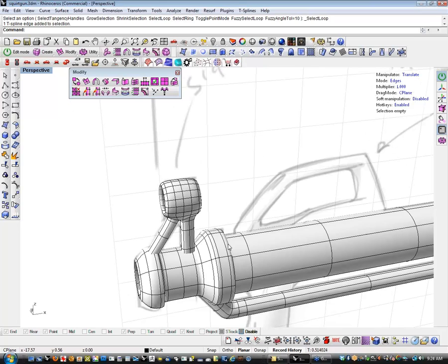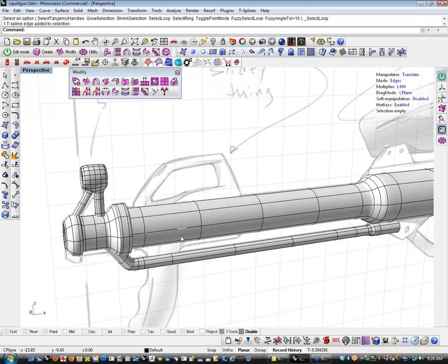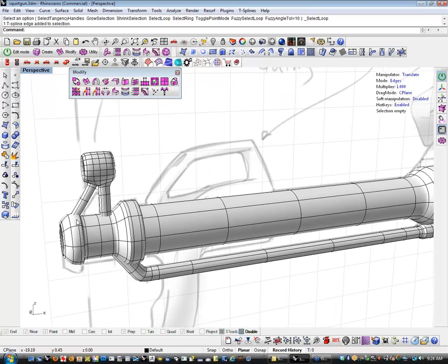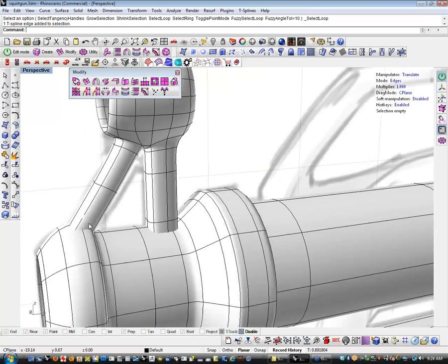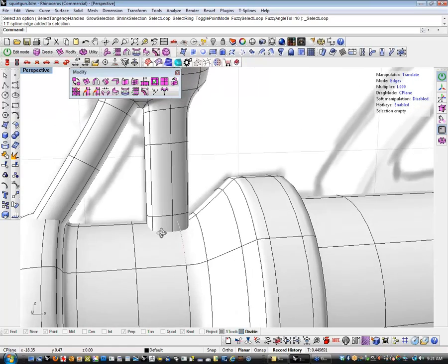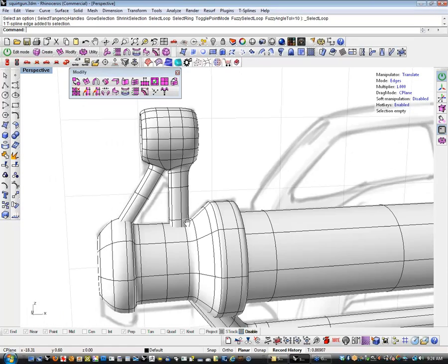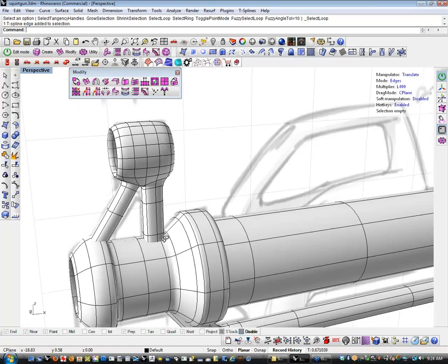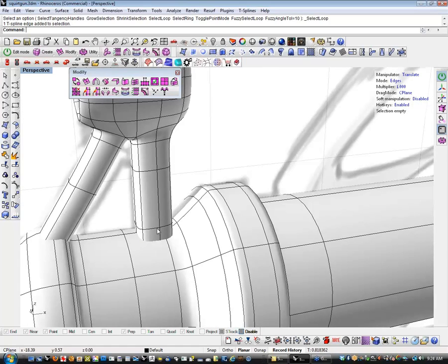If I'm not working with an engineer and this is going to be a NURBS model that has to be an IGES output or a STEP output or something like that, I'm going to have to translate this to NURBS anyways, and then in that case I'm going to want to do the fillets. In this particular case, I want to have the control of having these two things be separate parts and then manually going into fillets later.